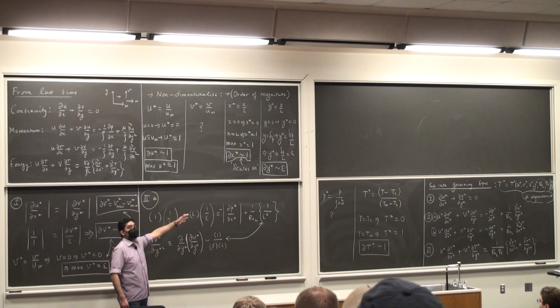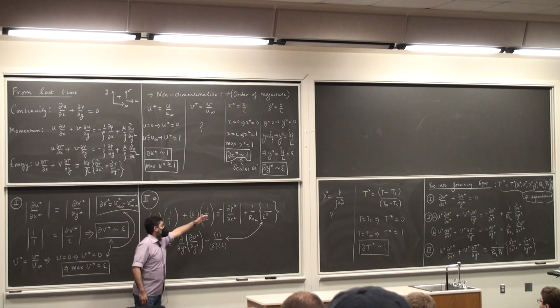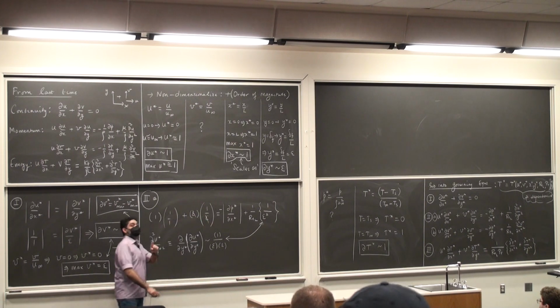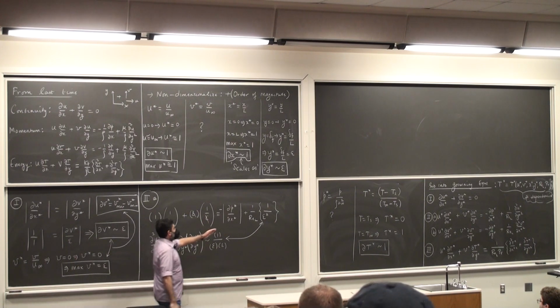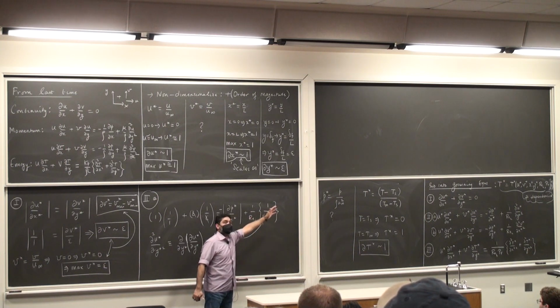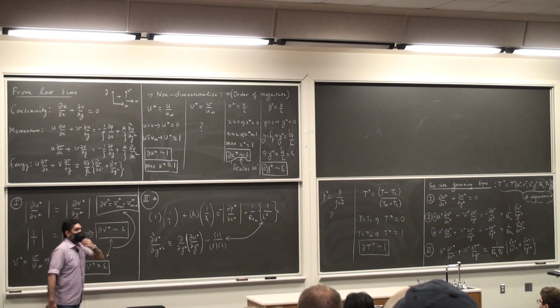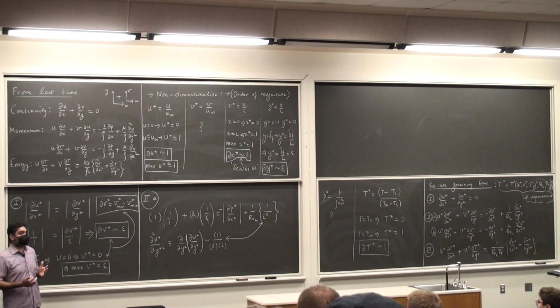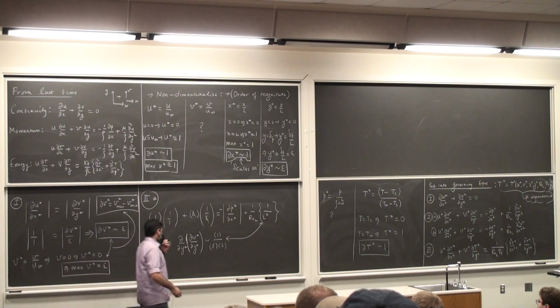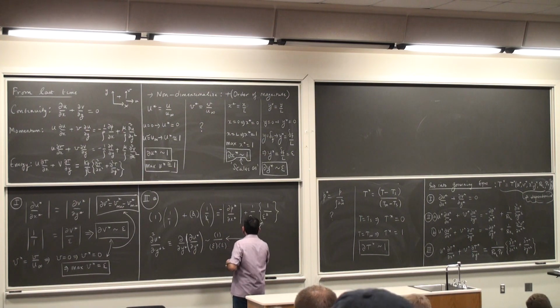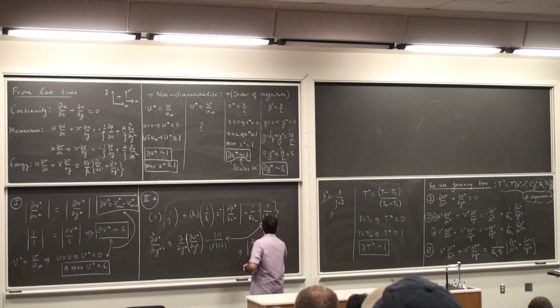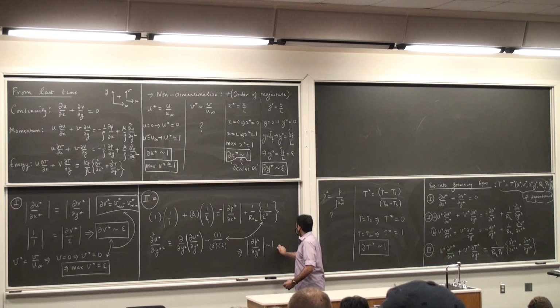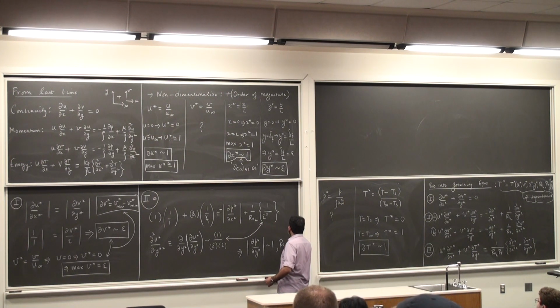The right hand side has to be the same as the left hand side, which means that dp star by dx star has to scale as 1, and this entire set of terms here have to scale as 1, which means the Reynolds number scales as 1 by epsilon square. So the Reynolds number is not a small quantity, it's a fairly reasonably large quantity, but still less than 10 to the power 5. So this tells us dp star dy star scales as 1, and the Reynolds number scales as 1 by epsilon square.